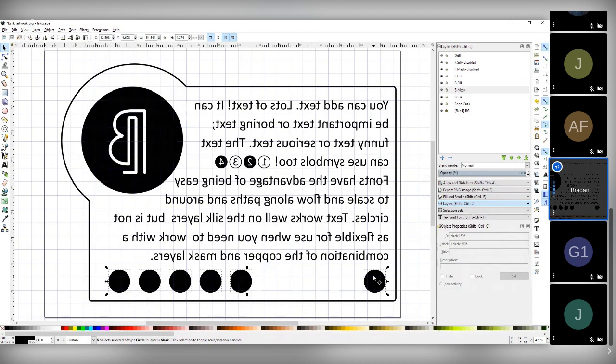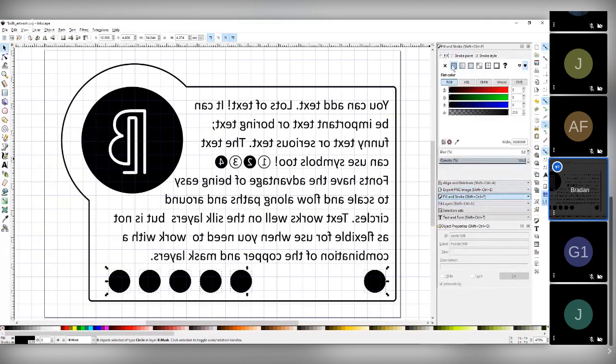The SVG plugin will filter out anything that is a transparency below a certain threshold. So that's a handy thing if you want to put notes on here, reminders, or reference points, but you don't want that to end up in the footprint: just set their transparency to something below half. That's the default. But let's just make it so that we can actually see this. I'll quickly make these red just so you can see them.